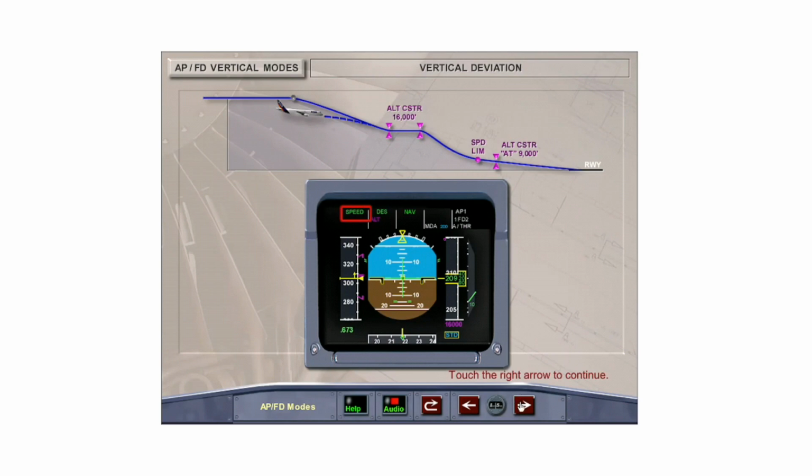If the aircraft falls below the vertical profile, the speed will reduce to the lower limit of the speed range scale in an attempt to regain the profile. If this is still not sufficient, the aircraft reverts to speed mode. The thrust is increased, and the vertical speed is reduced until the aircraft once again intercepts the vertical profile.